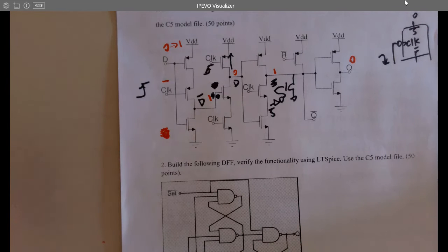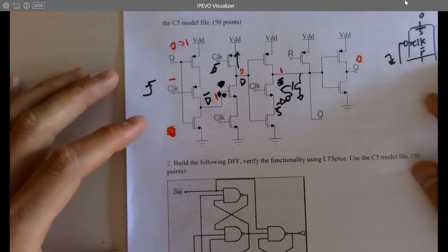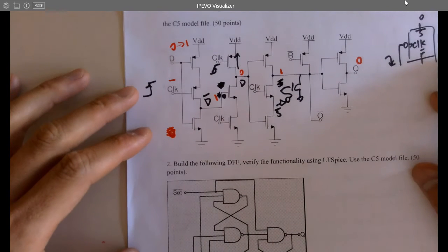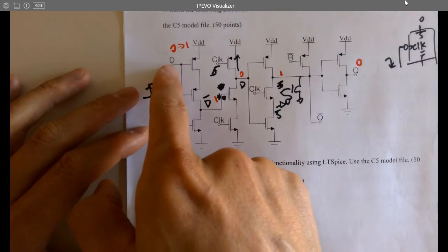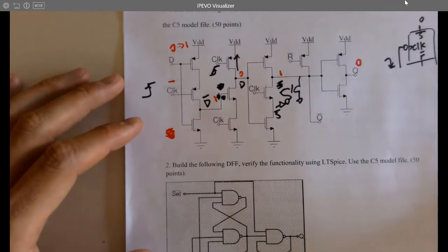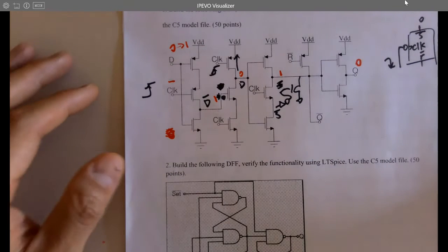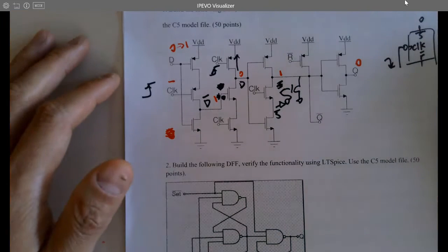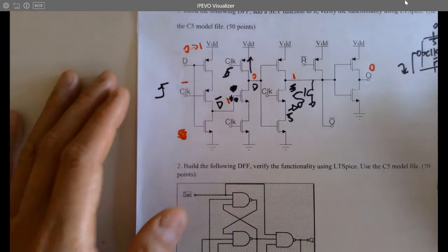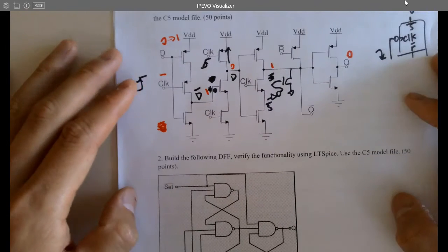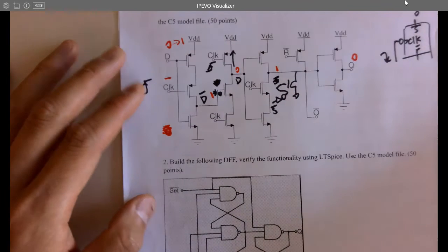Is it rising edge triggered? Is it synchronous or asynchronous? Since we are looking at the rising edge, D becomes Q immediately. It doesn't have to flip back. You are not waiting for the falling edge, remember? We haven't arrived at the falling edge yet. We're still at the rising edge. Just slow it down: rising edge and then logic high. It's not being changed.